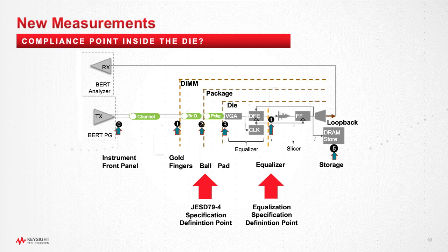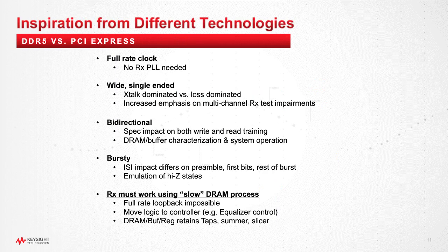And this is a couple of examples of the monkey wrenches, if you will, that are being thrown into the mix when we go past DDR4. There's really a whole set of things that are different between memory interface and a traditional high-speed serial interface that need to be taken into account when figuring out just how do you do a design that runs faster than 3.2, and how do you specify a set of devices that can support that.